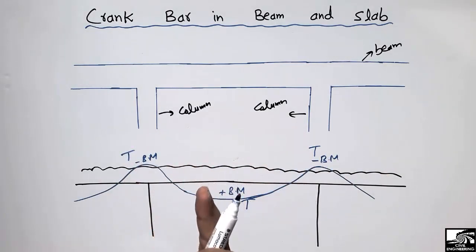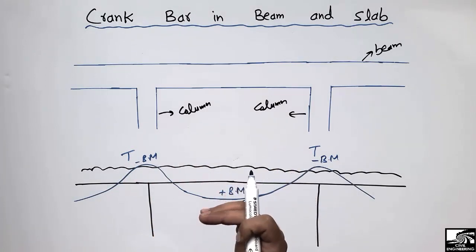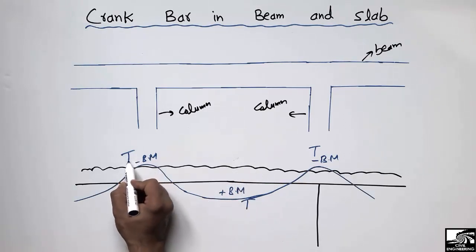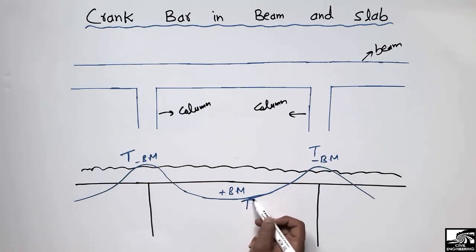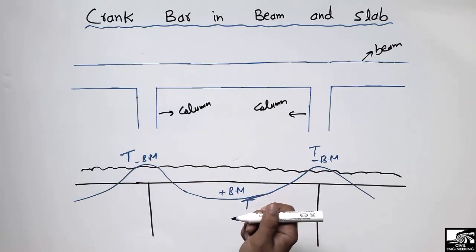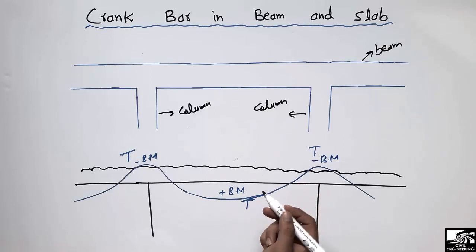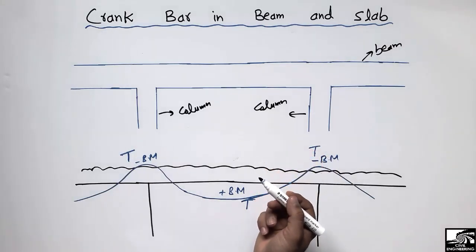If we say that we have negative bending moment, it means that we have tension in our structure member at the top surface of the member. So we have tension at the top of the beam here as well, while here we have tension at the bottom of the beam. And we know that the only thing that can resist these tensile stresses is the reinforcement, the steel bar. So we should provide the steel bar where there is tension in the structure member.